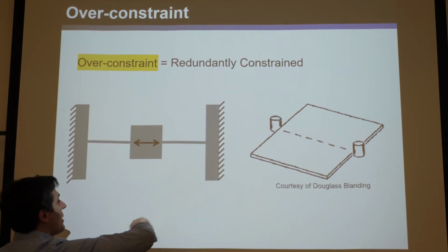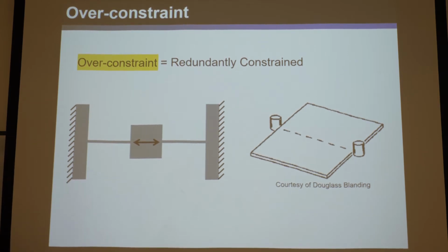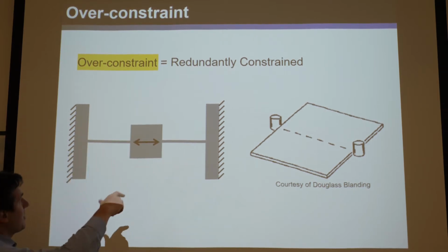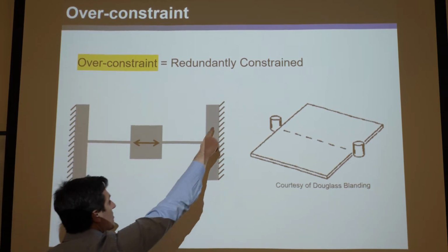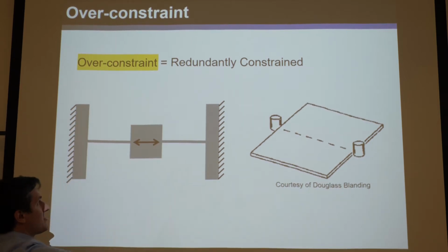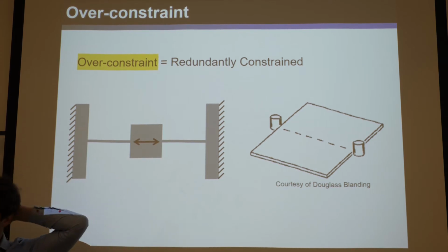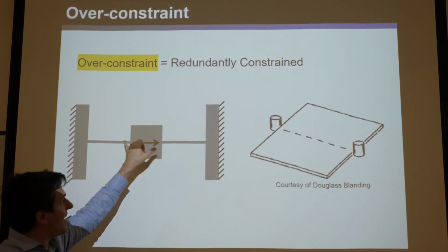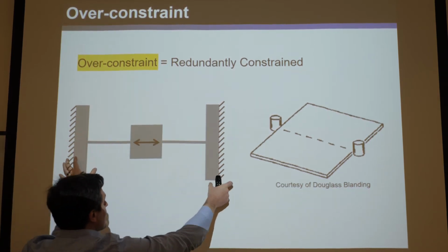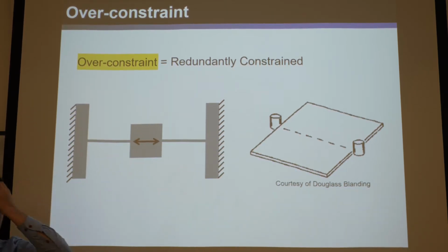This is a flexure system, and if I ask you, is this a parallel or serial system? Many of you might say it's a serial system because you see multiple rigid bodies. Well, you're wrong, because what you need to do is look carefully and see the hatching tells you what's grounded, and you might as well think of this as one big rigid stage here that's just grounded. So we actually do have 2 rigid bodies connected directly to ground by flexures. And yes, these wire flexures are in parallel. They may look like they're serially stacked, but they're not, because this is one common ground, and these are directly connecting it.